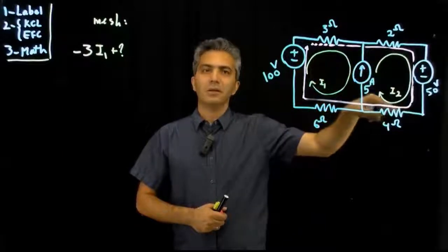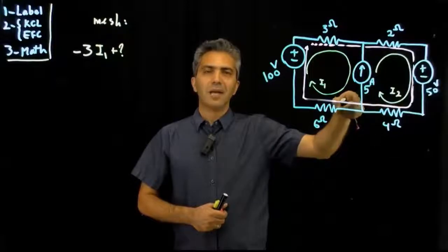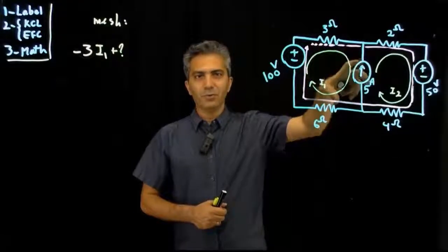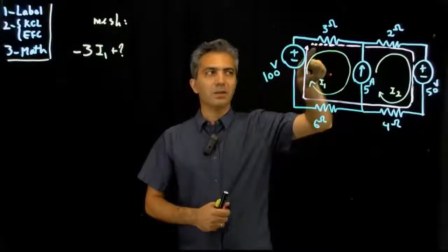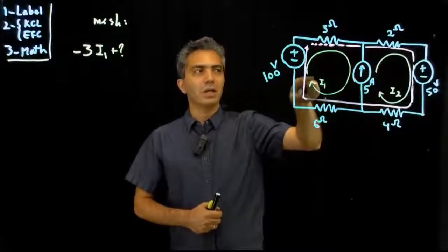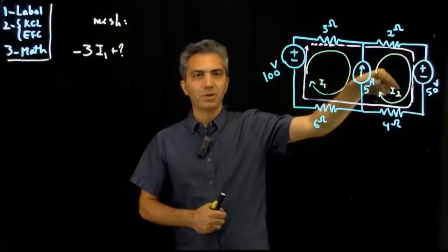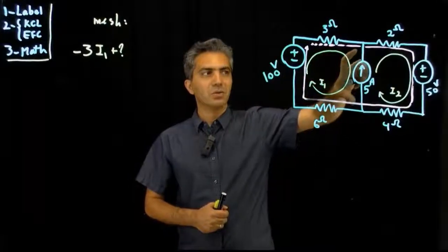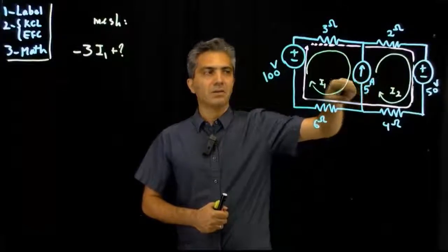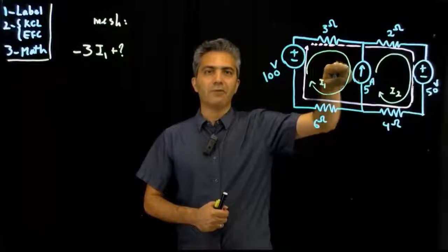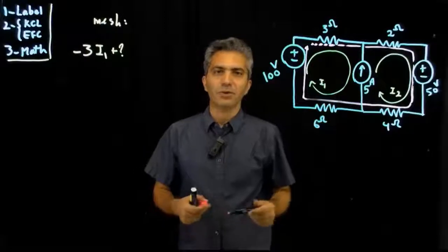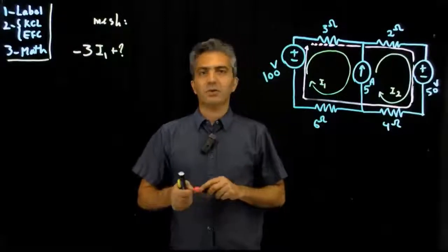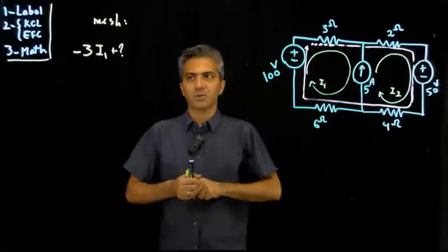And here the motivation is exactly the same, but a dual of that in the domain of voltage as opposed to current. So this super mesh includes more than one normal mesh, and the motivation is to define it such that I don't have to account for the voltage across a component for which I don't have an equation, in this case this current source.